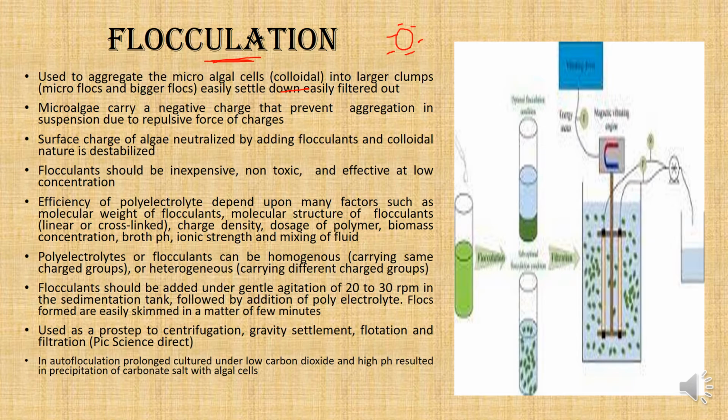So these flocculants are basically substances that in water dissociate into various charged units, and these charged units neutralize the negative charge on the surface of the algae.